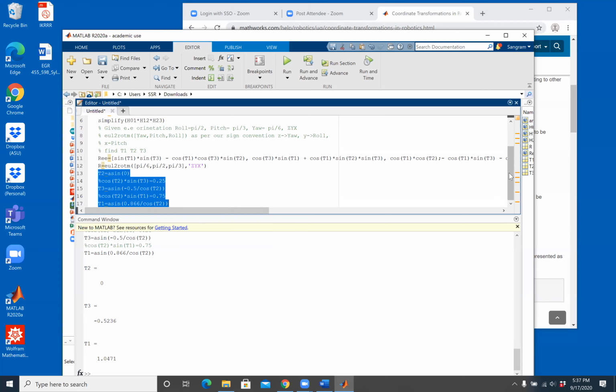So I just want to clarify the mistake I made earlier. The default MATLAB does not use the coordinate system that is used in robotics. In robotics, there are 12 combinations of Euler angles. Out of that, we usually use the ZYX Euler combination. So whenever you convert given Euler angles to rotation matrices, as you have seen from my mistake, depending upon what order of rotation you specify, your rotation matrix is going to be different.